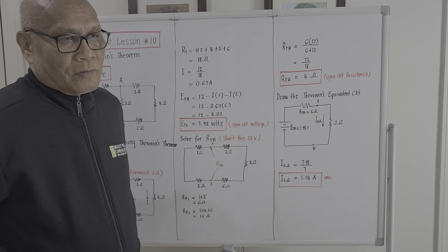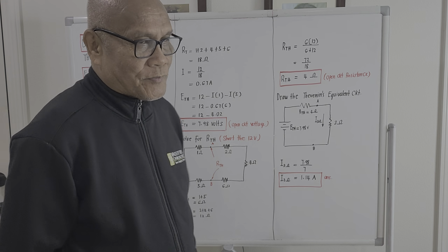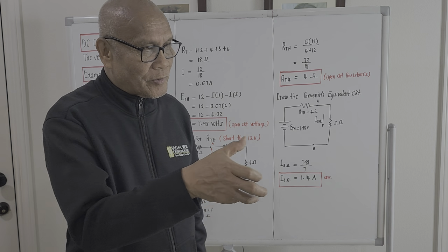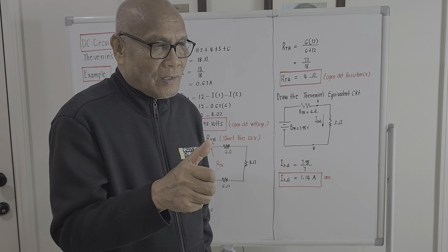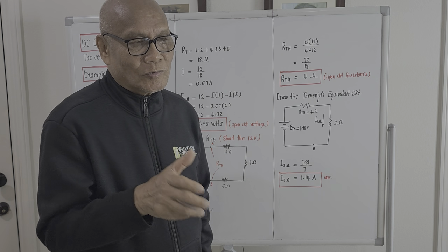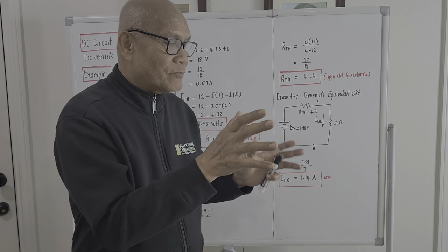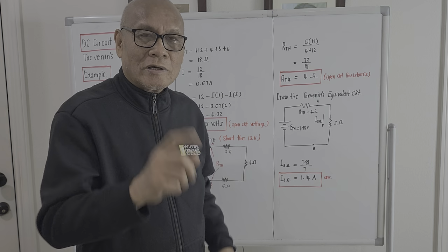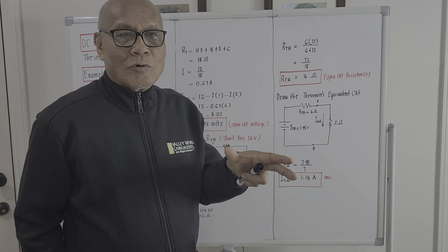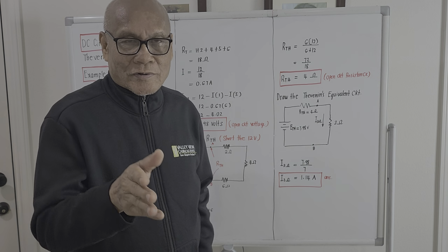theorem. The last time around, I discussed the so-called Kirchhoff's voltage and current law and the so-called computation of current passing through any portion of a circuit. And the next topic after that is actually by using the so-called total resistance method. And by using the two solutions from the previous discussions, actually we came out with the same answer. The current passing through the 3 ohm load, assuming the same problem, is actually 1.14 amperes.